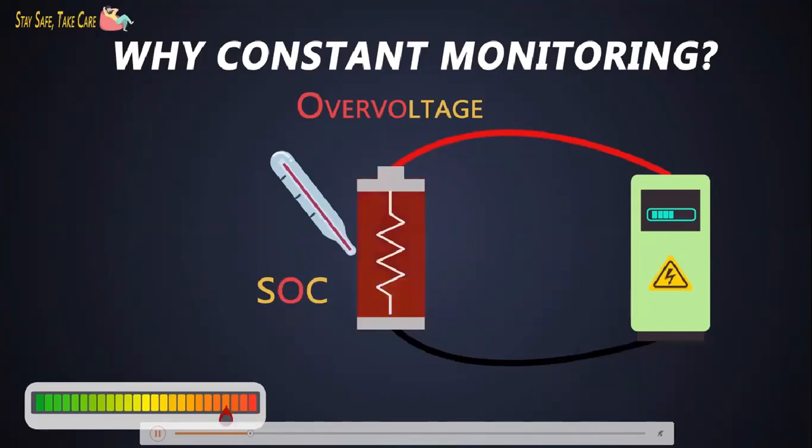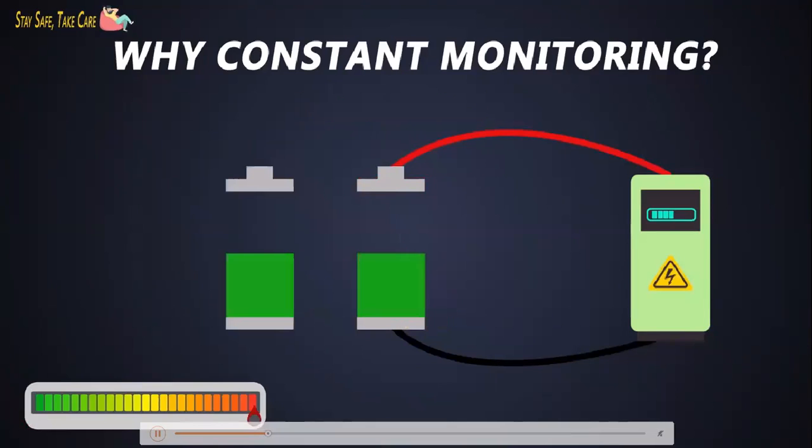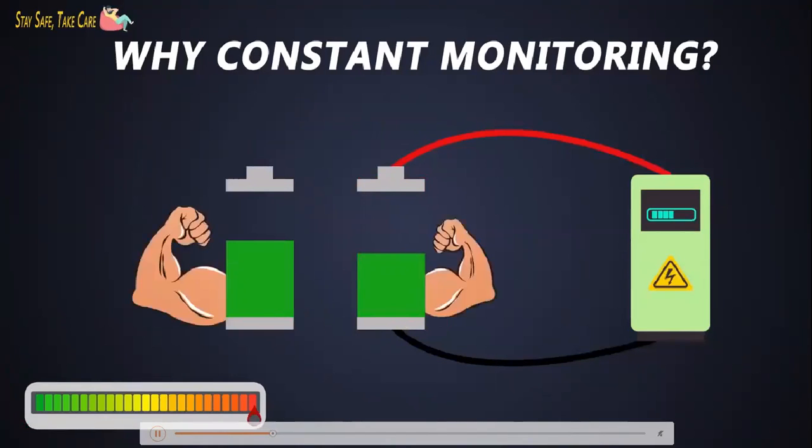On the other hand, if the voltage applied to the battery is lower, it also leads to over temperature. Over voltage and under voltage lead to a temperature which degrades the battery life, and if we use the battery at a temperature lower than its specific range, then its capacity decreases.